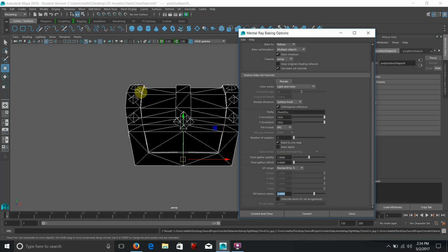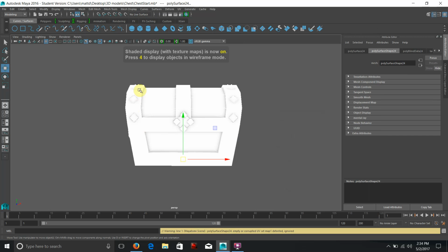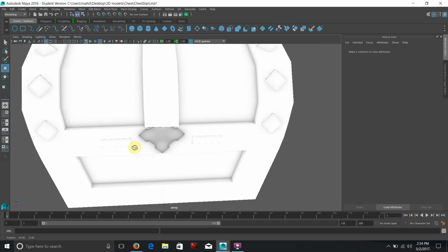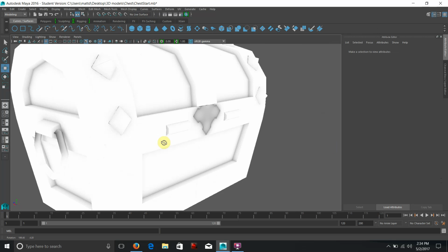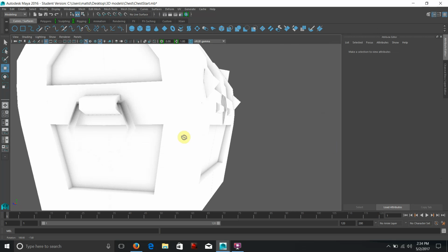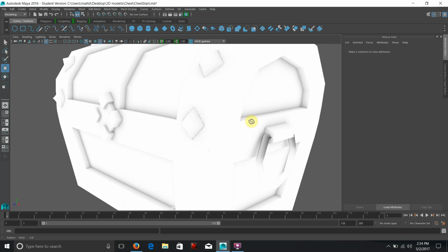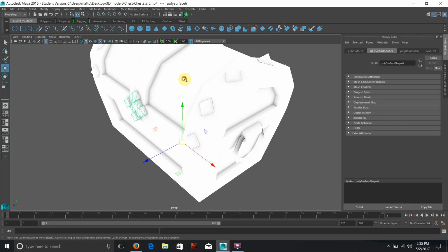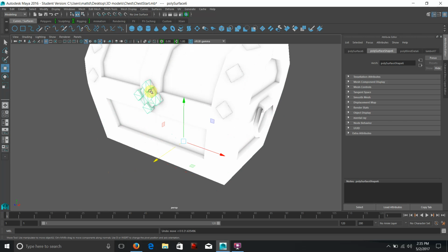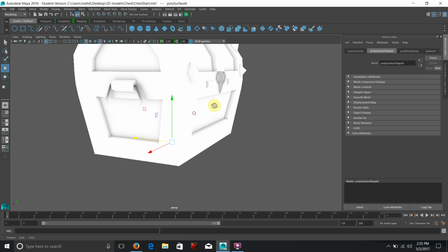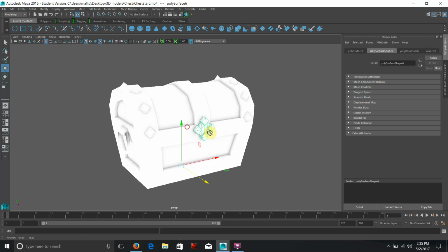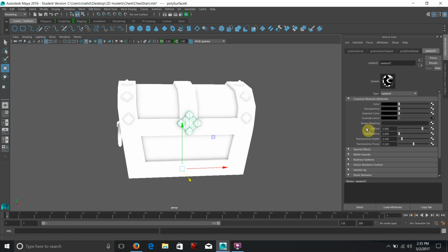So what it's doing is actually calculating the distance, and there it is, it's done, between the different objects, and what it's done is actually baked a shading map. Now, there's some inconsistencies to this map, one of which is this area here on the back. What happened is because this person UV'd it and stacked the UVs, if I remove this area, you can see it's calculating the shading and it's actually duplicating to the back. So we can go ahead and erase that later on if we want to. But for now, this will work just fine.